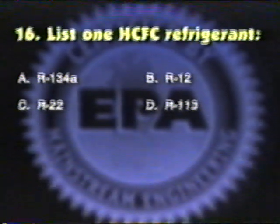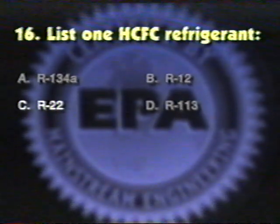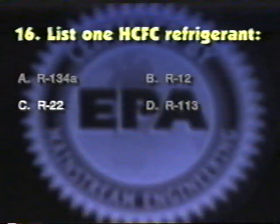The correct answer is C. R22. Be sure to know which refrigerants are HCFCs. Remember, R134A is an HFC. R12 and R113 are CFCs.